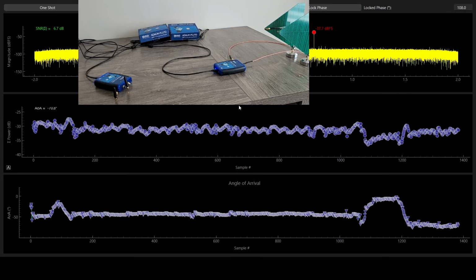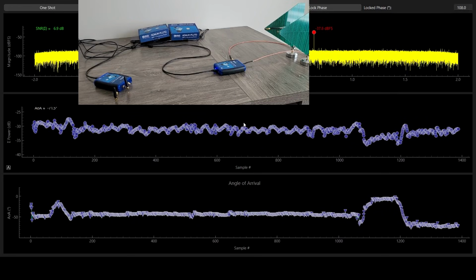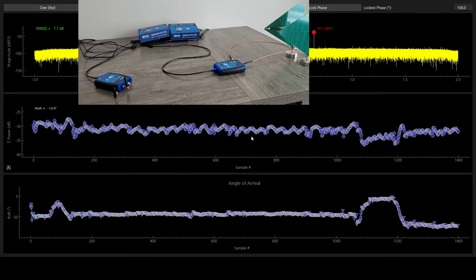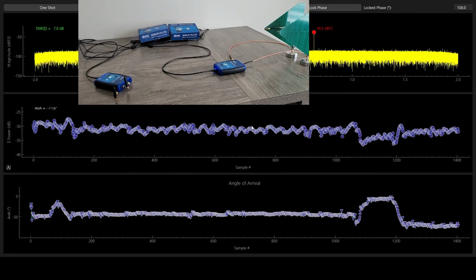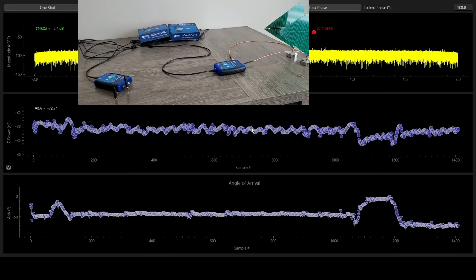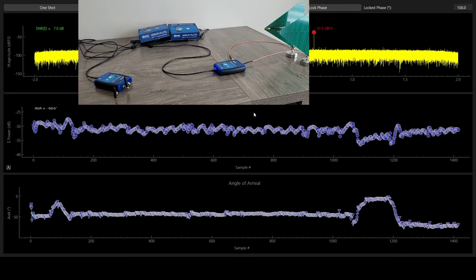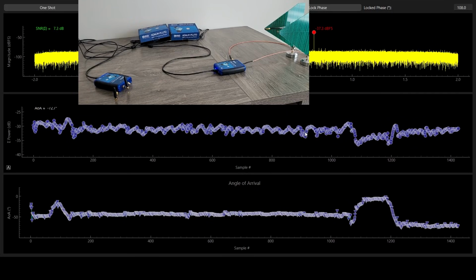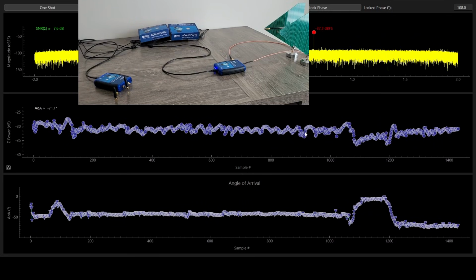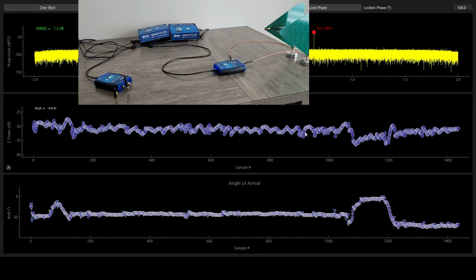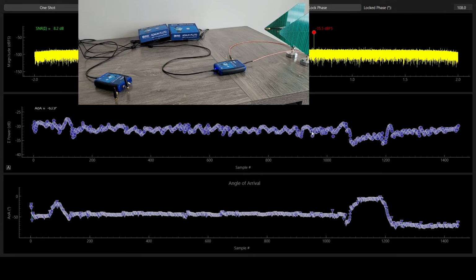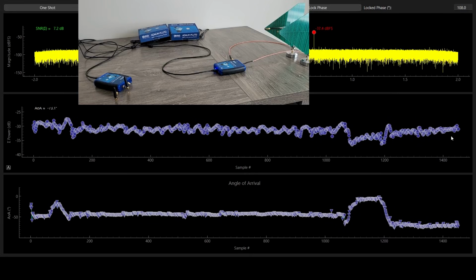So as long as we can calculate the difference between those channels correctly, and add the RX channels constructively, even if the RX position changes, because we calculate the phase difference and correct it and then add them constructively, our received power stays the same.